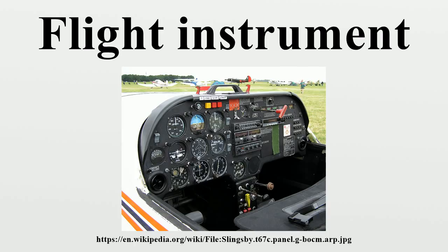Flight director systems. These include the horizontal situation indicator and attitude director indicator. The HSI combines the magnetic compass with navigation signals and a glide slope. The navigation information comes from a VOR, localizer, or GPS. The ADI is an attitude indicator with computer-driven steering bars, a task reliever during instrument flight.